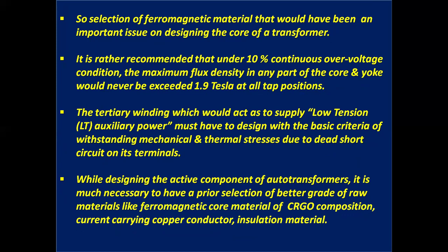Most important, the tertiary winding, which would act to supply low tension LT auxiliary power, must be designed with the basic criteria of withstanding mechanical and thermal stresses due to dead short circuit on its terminals.